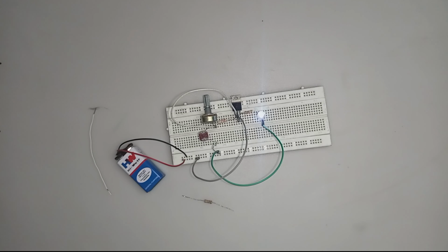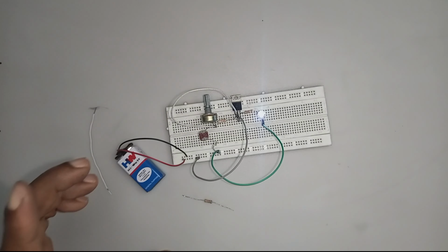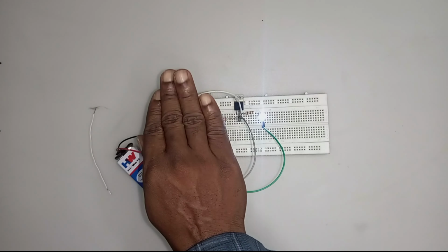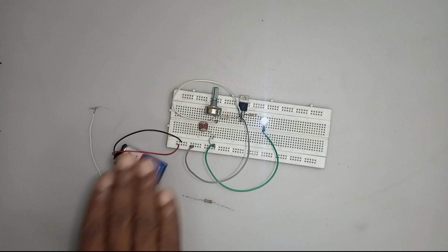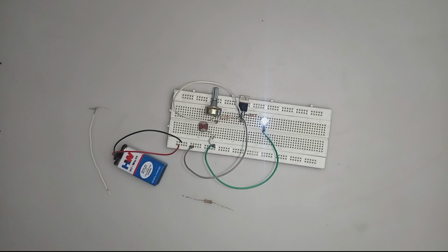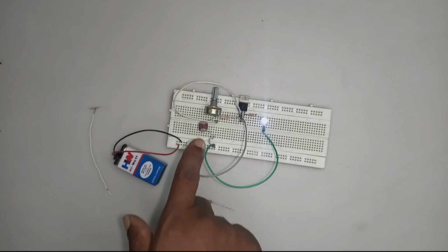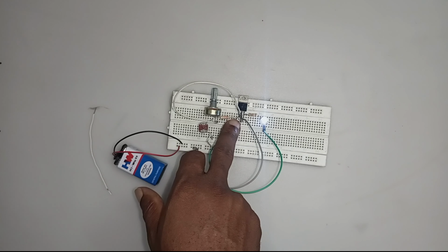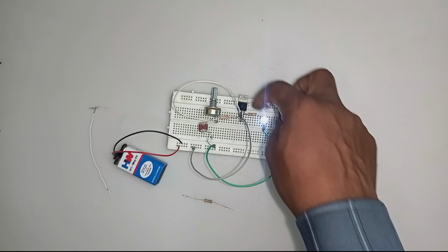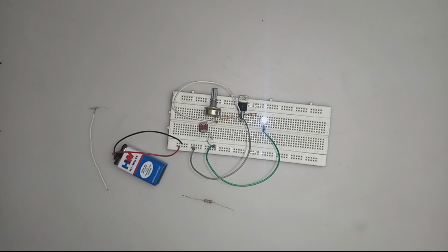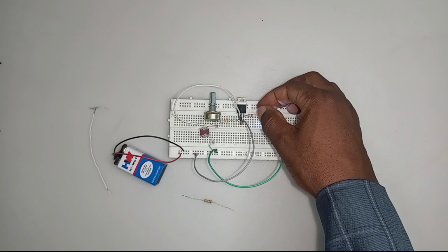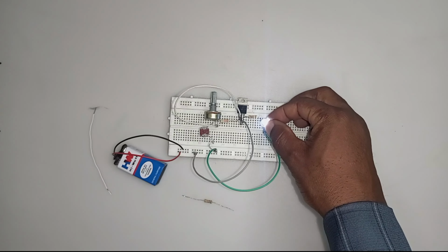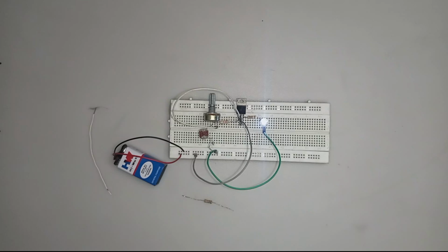But when the light is taken off and then darkness is introduced to the light dependent resistor, its resistance will increase. When the resistance increases, then current has no choice than to pass through the 22 kilo ohm resistor, and then it will continue and get to the LED. This resistor is only meant to reduce the amount of current that reaches the LED in order not to burn it. That is all. So this is a very simple circuit that you can implement at home for fun.